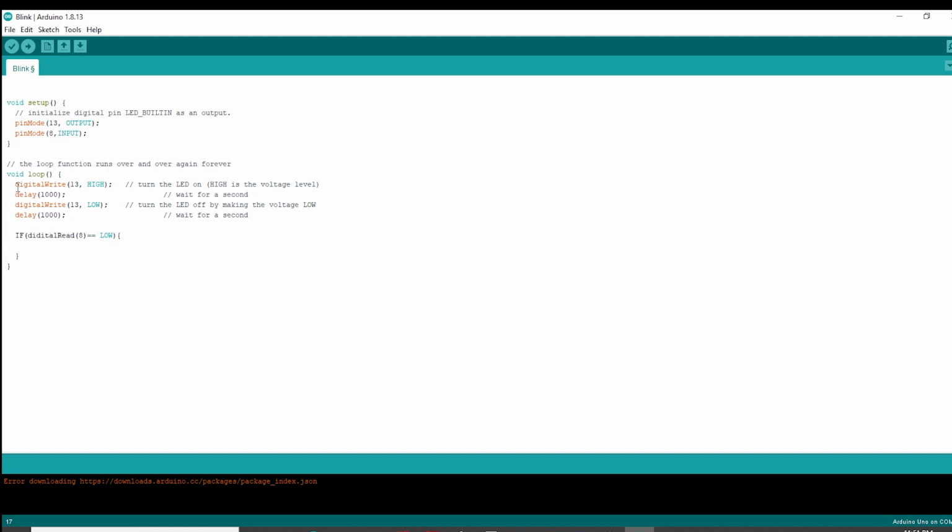We can copy this into our code here. So what we're doing is, if this condition is met, we need pin 13 to be written high. Delay it, for this case, 200 milliseconds. Then write it low and delay it for another 200 milliseconds. Okay, so I made an obvious mistake here, and let's see if we can compile this.